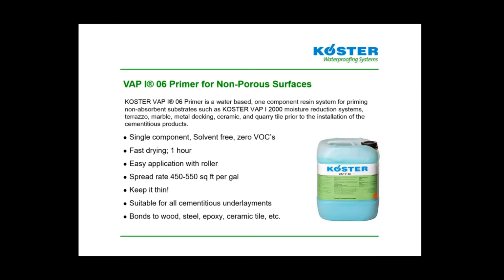It's a one-component, 0 VOC, fast-drying product that dries in about 45 minutes to 1 hour, depending on the environmental conditions. Spread rate around 450 to 550. We like to say 500 square feet per gallon. It's relatively thin. It's a dip and roll product,